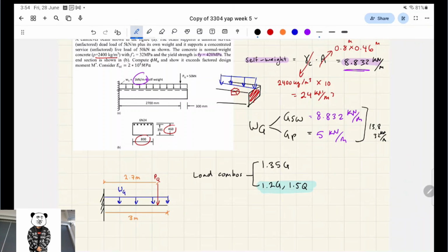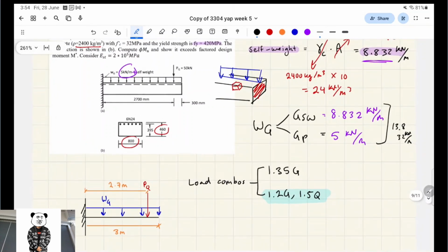Okay, another question. What kind of beam do we have here? Cantilever. Where are the most moments, like where's the max moment on a cantilever? Furthest away from the fixed. Very end. Furthest away from the fixed. Which end? Furthest. So here is the max load, like highest bending moment.